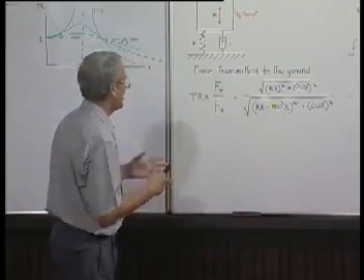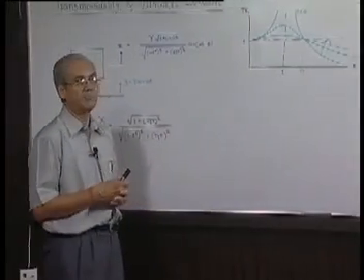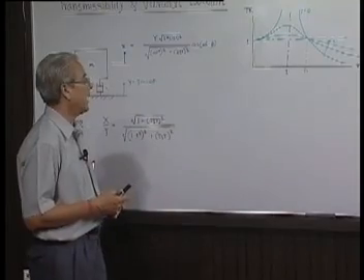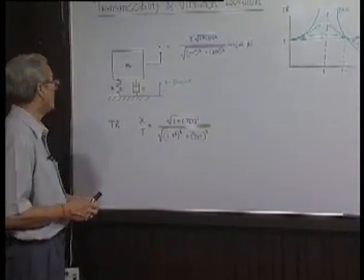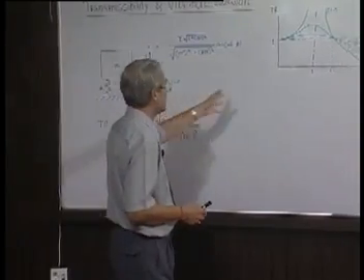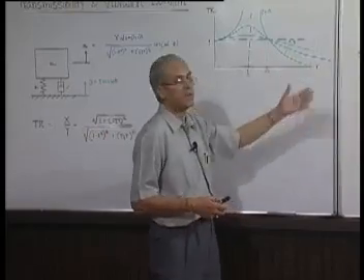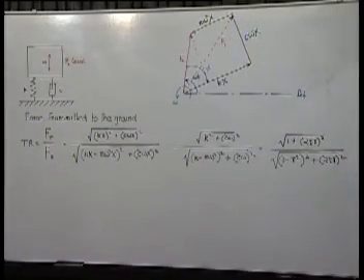So, this technique of isolating a system from the environment is called isolation, and the quantity which dictates to what degree one system has been isolated is called the transmissibility. And for simple systems like this, transmissibility behavior is like this and expression is like that. Best will be perhaps if we solve a problem.